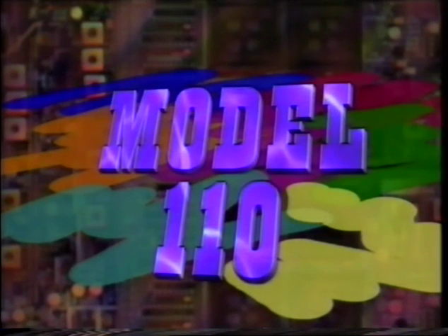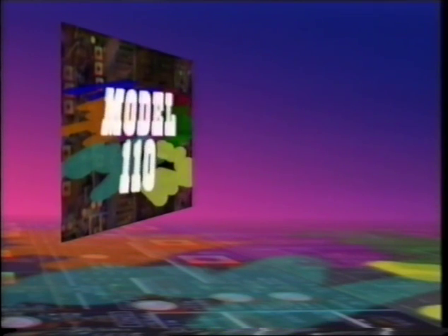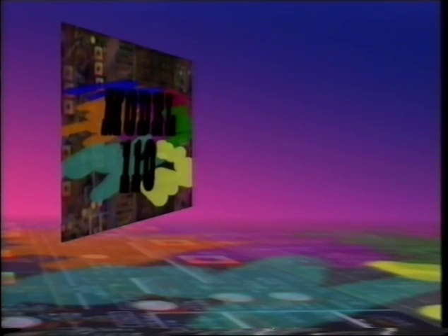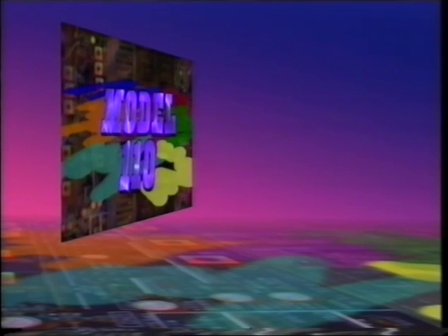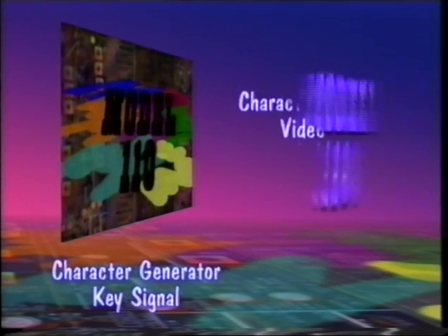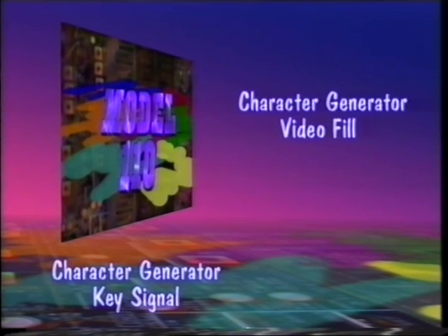The switcher can also perform keys, where a part of one picture is inserted into another picture. A key requires three signals: a background, a key source or hole cutter, and a key fill made up of a video signal or a matte signal. If the key fill is the same as the key source, then it is termed a self-key. If an external source supplies the hole cutter, then you have an external key.